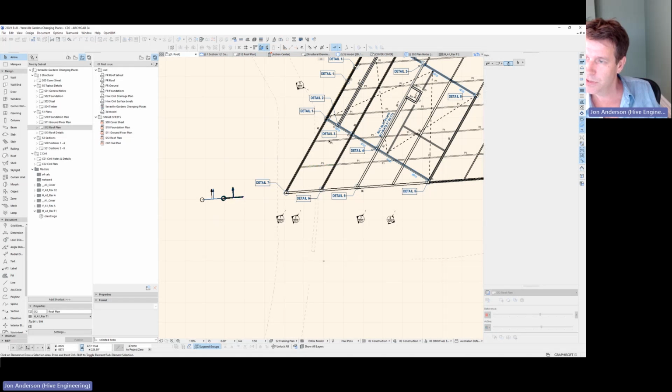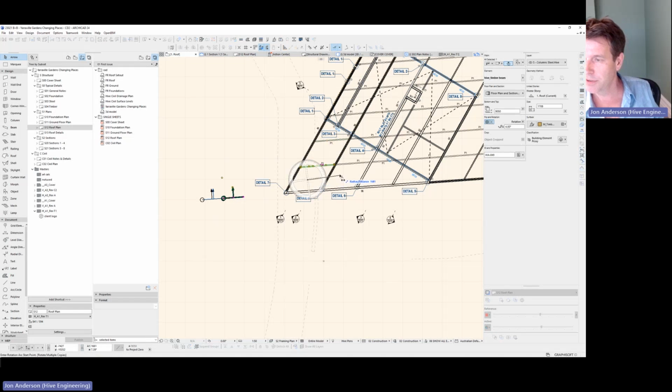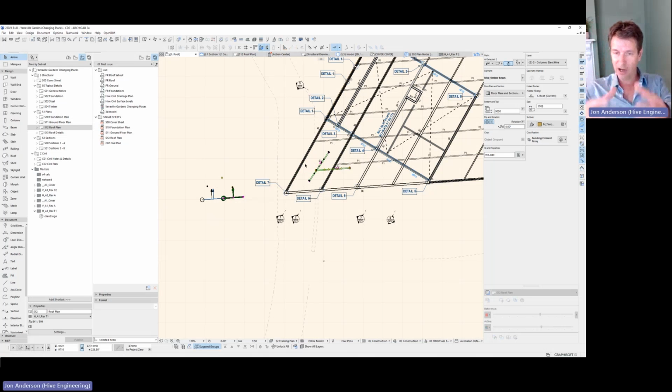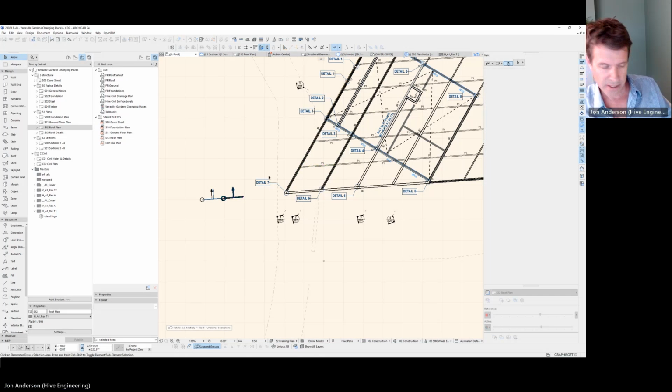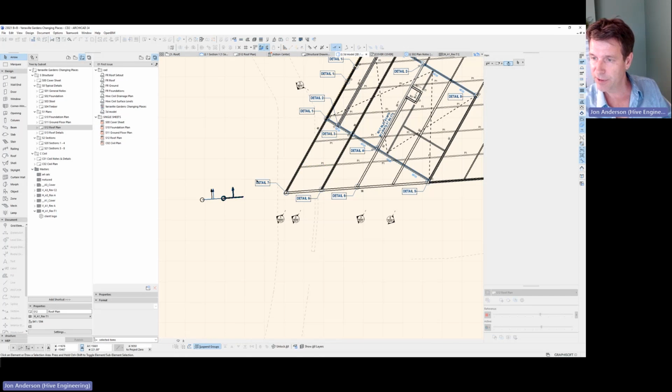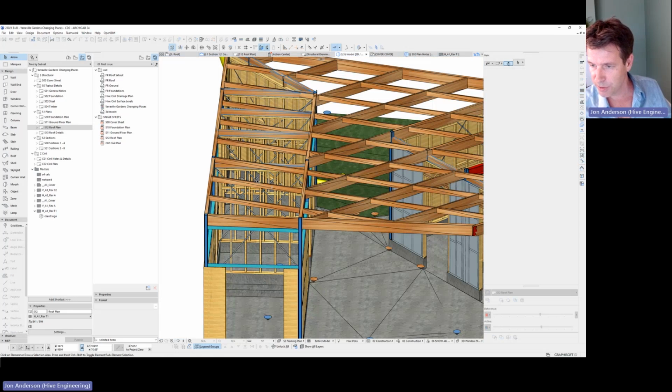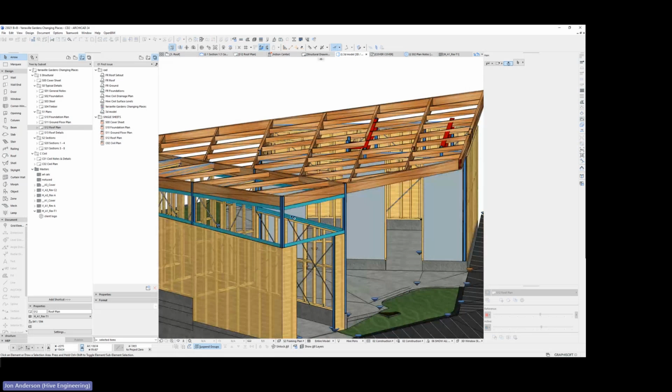Each of those elements is linked to the pitching line of the roof, and then it can automatically calculate wherever it is, it's still pitching off that line. That gives them the height, the slope, and the rotation. And that's how I get the model to look accurate. And then I've also got the walls and the typical simple project.